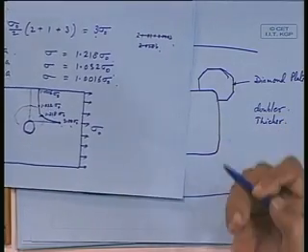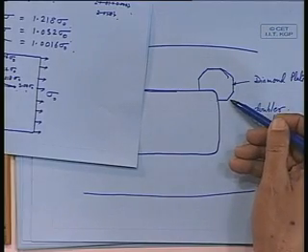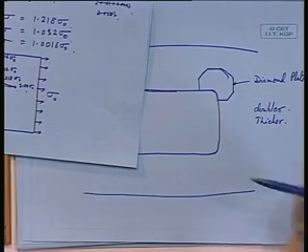But these days we are not going for the doubler plate, just because if you are having two plates welded, there is every likelihood that some gap will be there, and there will be a passage for the oxygen to get inside, the water will go there, the moisture will be there, and there will be a galvanic action between the two plates, quite likely. Okay. And therefore inside you cannot protect it, so you just simply remove this part and change it with a thicker plate at this edge here. So all these areas are strengthened to take this additional stress value.